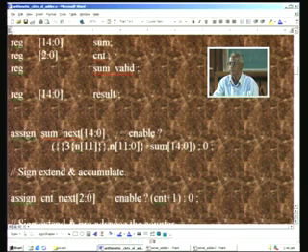This is the very first assign statement, in order to compute the sum next, and this is done by using a mux, which you are already familiar with, and enable is the one which will enable the computation of the sum. Actually, to start with, when we have n naught input, it will appear here, and sum is initialized to 0, which we will notice a little later on.